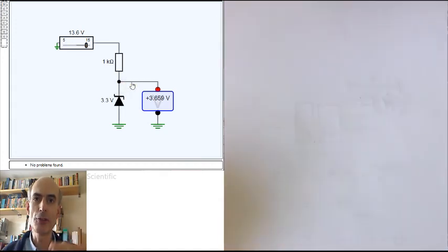We've stabilised the voltage. It's a way of producing a voltage reference, a point in the circuit that maintains its voltage no matter what the input voltage to the circuit is. Quite useful for battery-powered circuits, where the voltage that you get from the battery is decreasing as the battery discharges, but the voltage at this point in the circuit would remain comparatively constant and could be used as a reference to compare other voltages to. We'll see quite a few applications of this type of circuit in later videos as well.